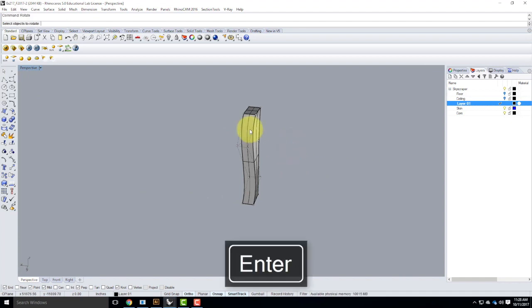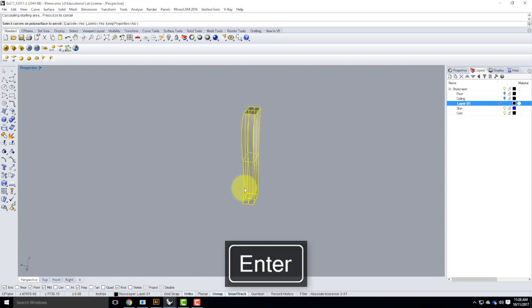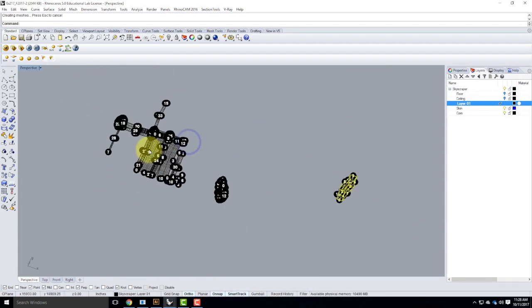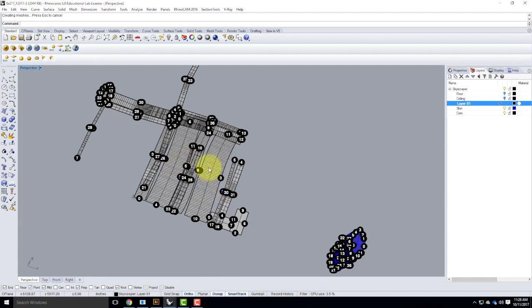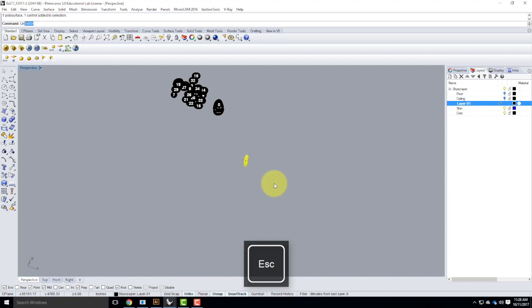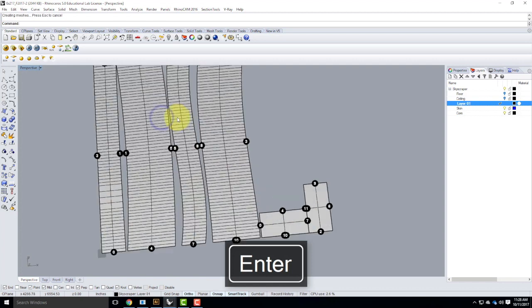I can unroll this surface as well, and this one will assemble a little bit easier. So there it is. I can do unroll surface. There's my pieces. Select. My options are the same. This, unfortunately, put the pieces right on top of the other pieces. So let me back up for a second there. Let me move these so that they're out of the way, and then I'll do this one. Unroll surface. My options are still set. Explode, yes. Labels, yes. Keep properties, no. I'll hit enter. I have fewer pieces this time. So there's my various pieces.